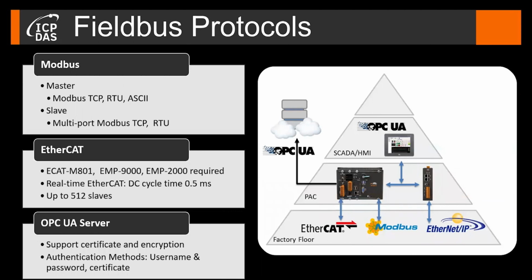Several field bus communication protocols are supported by our soft PLCs, such as Modbus TCP, RTU, ASCII, master and slave, EtherCAT communication for our EtherCAT-based motion controller, and in addition, Win-GRAF has a built-in OPC server that can transmit PLC data to remote OPC clients like HMI and Cloud Server.